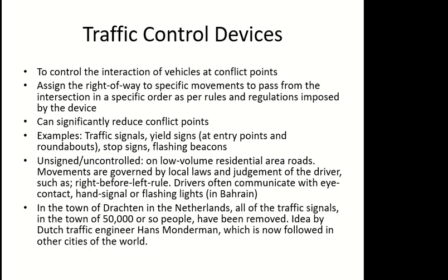Usually traffic signals are not preferred on small streets, because they usually create more delay, especially for low traffic conditions. The signal remains red and yellow, and during that time the vehicles need to wait.